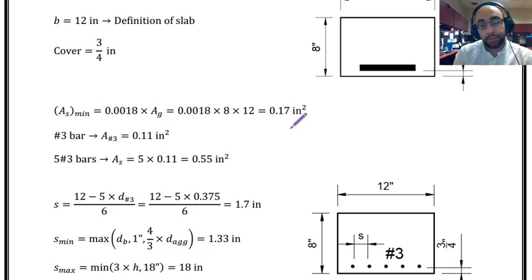That is possible, but when you have such a big reinforcement as your tensile reinforcement and just 1 or 2 bars in the section, it will create a huge amount of interaction stress between the reinforcement and concrete. And this stress concentration will create lots of cracking and increases the chance of having separation between the reinforcement and concrete.